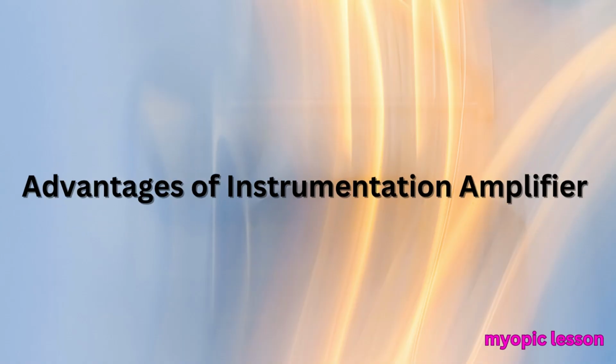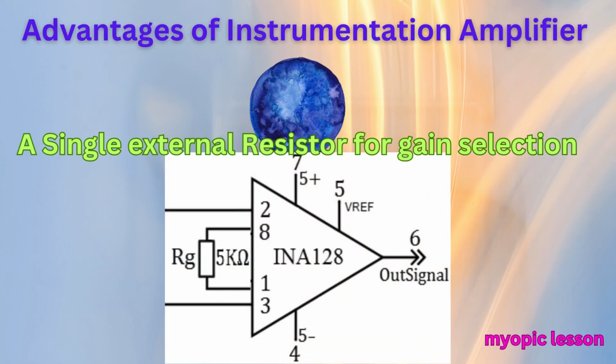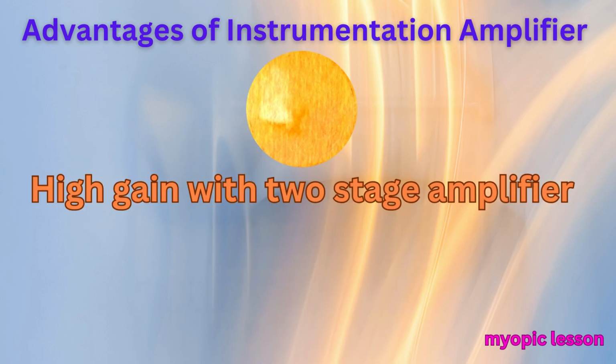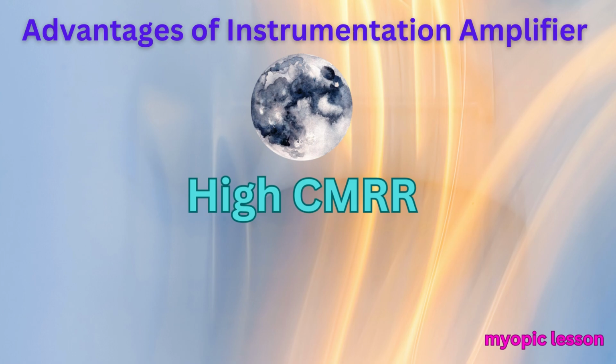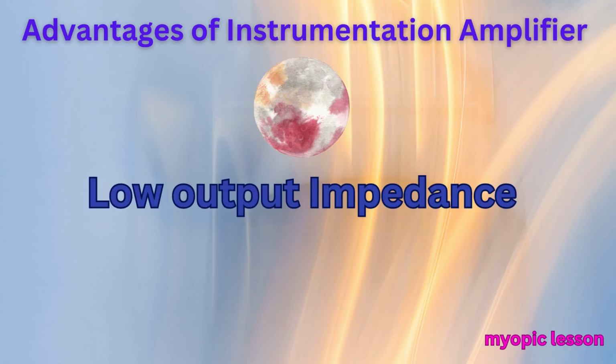There are a lot of advantages of the instrumentation amplifier. First, a single resistor connected externally to the instrumentation amplifier IC is used for gain selection. Second, the provision of two-stage gain makes it suitable for introducing a high value of gain. Third, it has high CMRR. Fourth, input impedance is very high, hence it does not load the system connected to its input. Fifth, output impedance is very low, hence it is not loaded easily by a system connected to its output side.